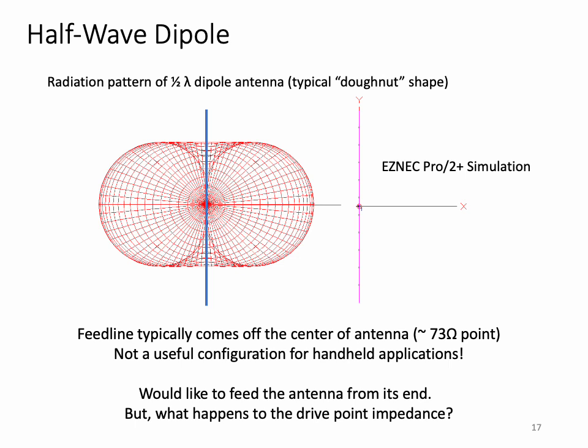In most cases, the dipole is typically fed from the center, where the driving point impedance is close to 73 ohms, making it a reasonably good match for a 50 ohm coax. However, in this vertical configuration, feeding the dipole from its center would produce a very awkward, if not impossible, mechanical situation. I have to somehow put the coax here, put it far enough away so it doesn't interfere with the dipole, and trying to mount this on a handheld would be a real bear.